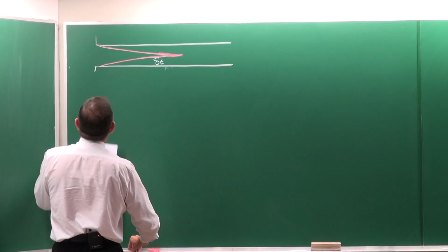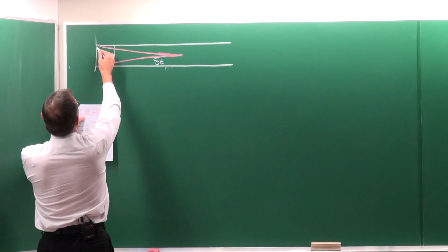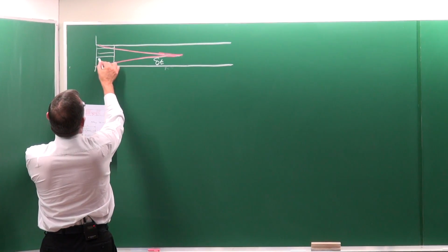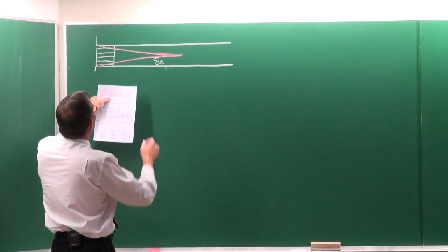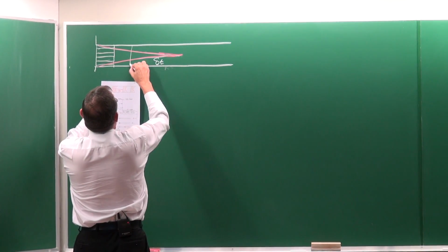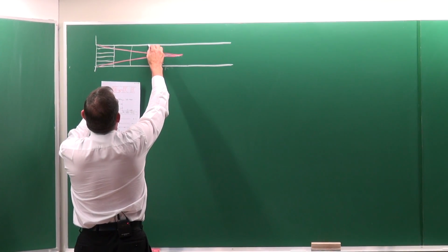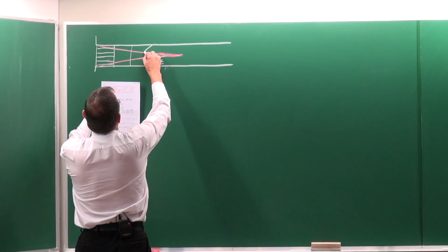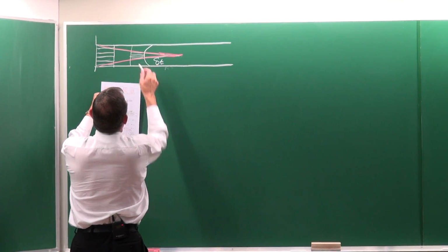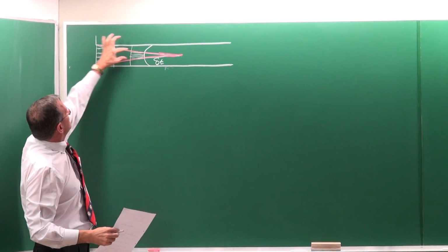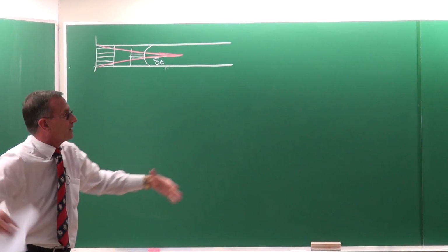So if I can try to make a good drawing of the temperature profile, here at the inlet it would be a uniform velocity, uniform temperature profile. Then, if the walls are at a higher temperature, we're going to get something like that. So here on the outside, between the two boundary layers, this temperature will remain constant because they do not experience the boundary layer.